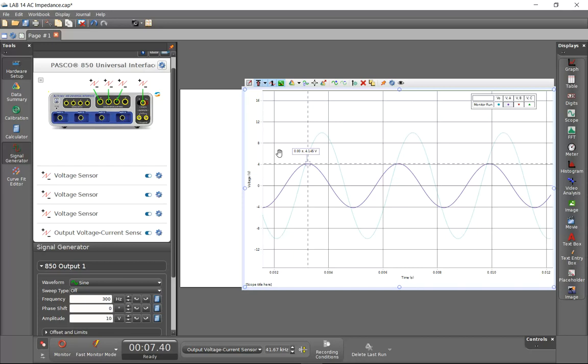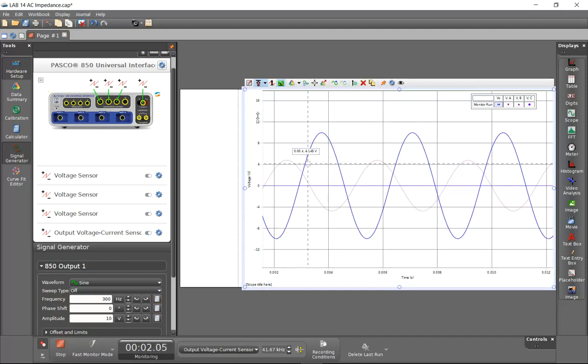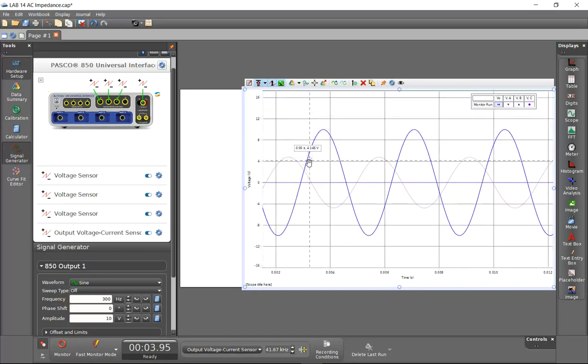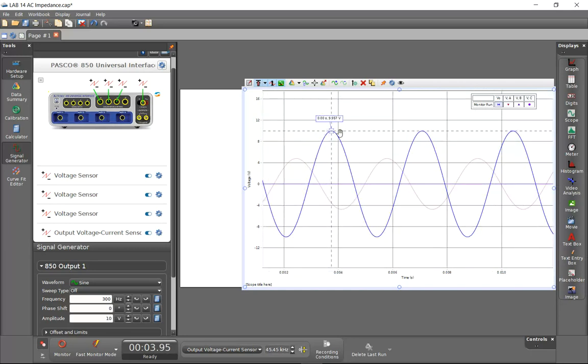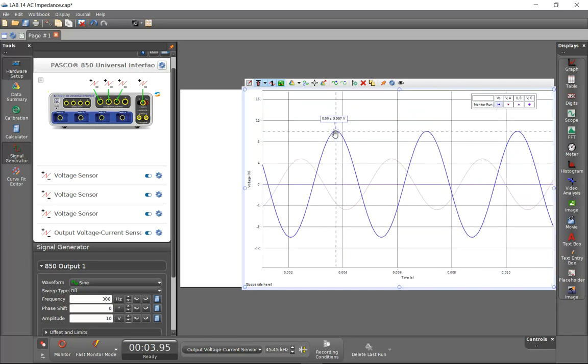So we have here 4.145 volts, good job, for the voltage across the resistor. Now I'm going to go to the voltage across the inductor and repeat. And so now the inductor, oh yeah, you lower the frequency. I was like, that's not what it was yesterday. So no, that's the source. You can always tell by looking at the legend up in the top right. The one that's kind of magenta-ish color is the one that we're looking at with our probe. And so we have 4.782.